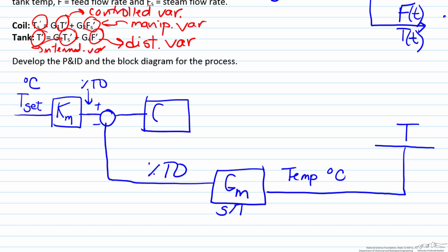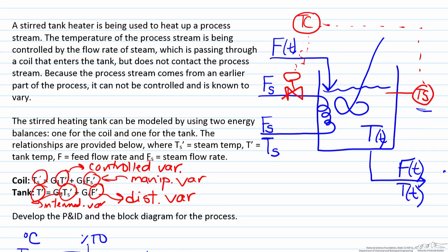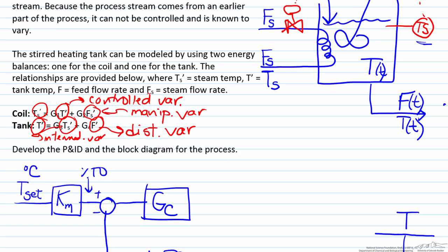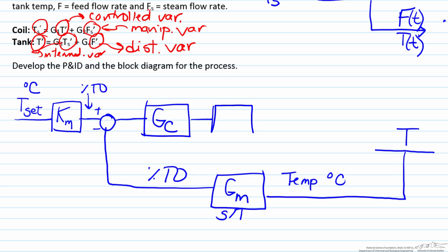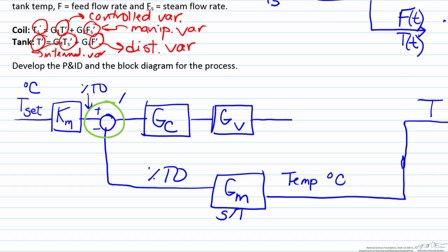From there, the controller will take the signal. Again, we look at the diagram here. The controller will take the signal from the sensor and compare it to the set point, which is something already programmed into the controller. Following that, the controller will then send its signal to the valve. So if we go back to the block diagram, GC will go to GV. Looking at the summing point here, the difference between these two is an error in percent transmitter output. So this is the error.